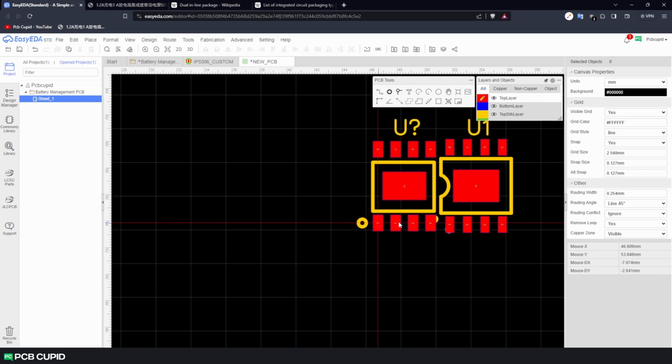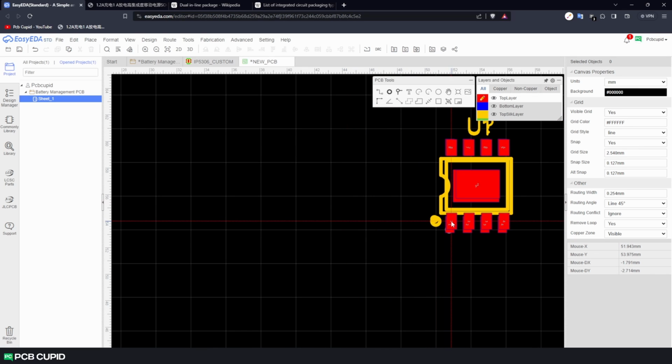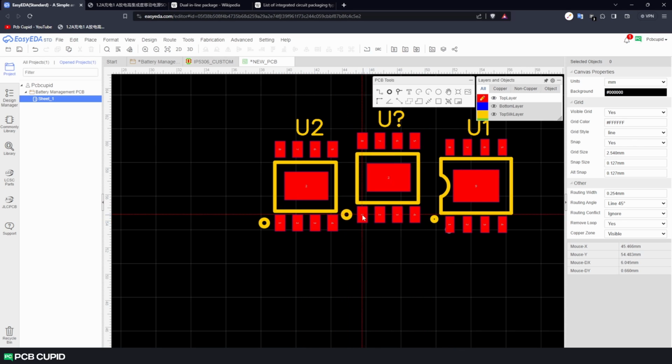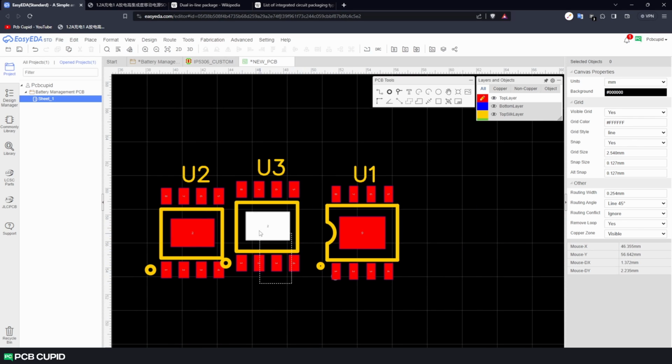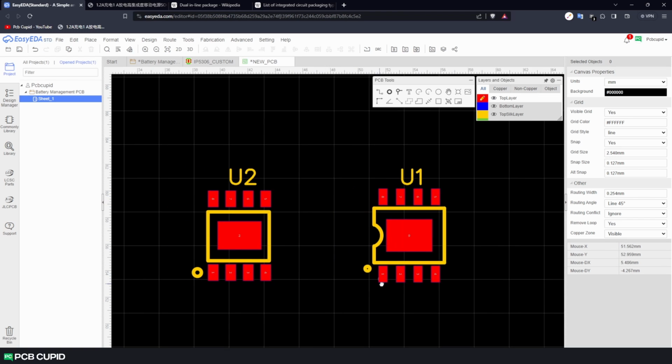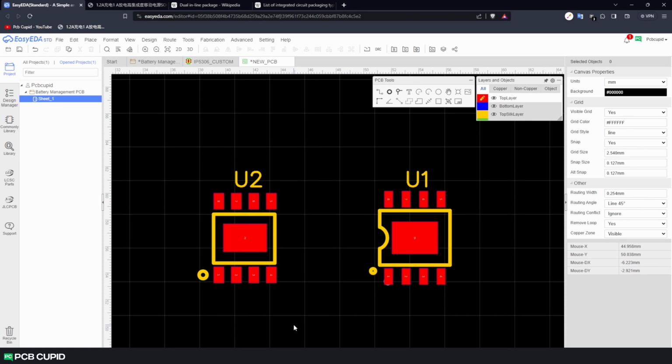As you can see, they look very similar, but with slight variation in the size of the pad because we took the multiplication factor 1.5 arbitrarily. And also because the silk layer looks much better with the notch on the default footprint. Anyway, this concludes the video. You can follow the same process not just to build an IC, but also to build any type of component you would like using EasyEDA's footprint editor.